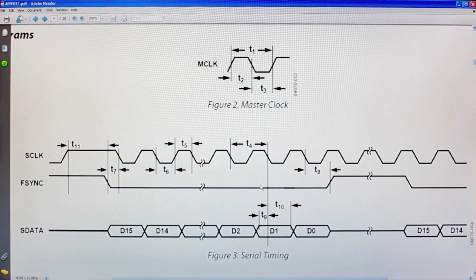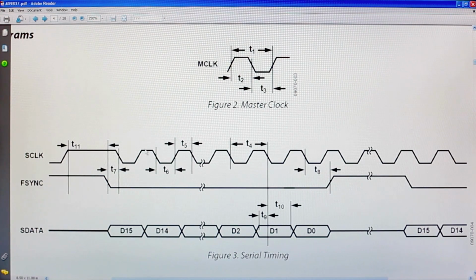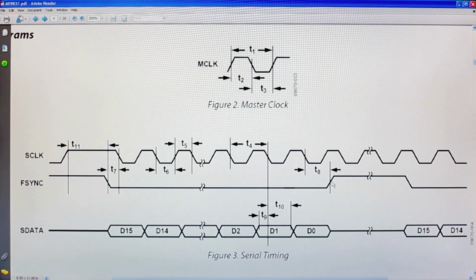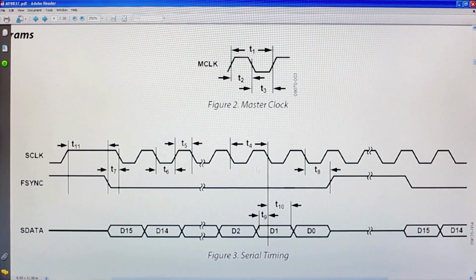I did put it on the hardware lines because I assumed at some point I would want to go to hardware. Honestly, this transaction is pretty easy to bitbang as long as you're paying attention to where you have to read data or send data. And it's not that bad. The thing to take away is that the longest time of any given thing defines how fast you can run the clock.